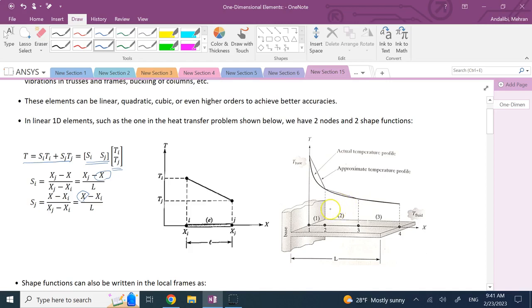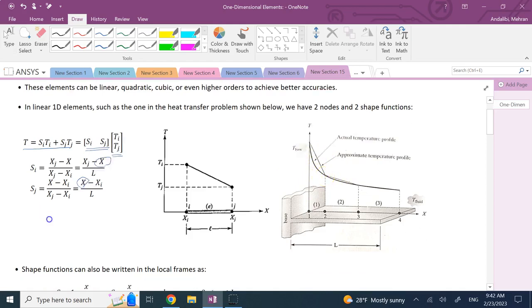And that's what we did in our ANSYS videos. You see I added a refinement, right? In the areas where I see big changes, like for example in the stress concentration areas around the hole, you see that I use smaller elements. So this is what you really need to keep in mind.